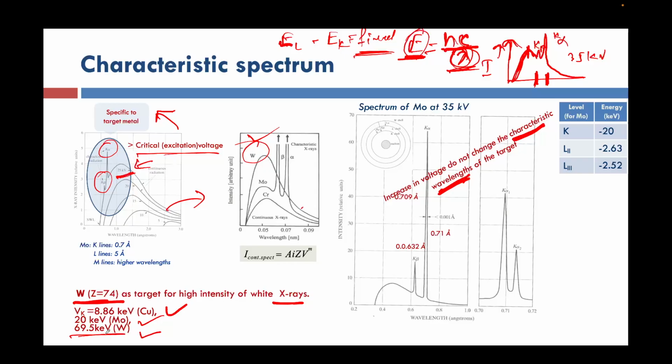This is also another reason why, as we might all have heard, in the laboratory we generally use copper X-ray. Copper X-ray is nothing but the anode, or target, material being made up of copper. This is one of the reasons that we don't have to apply very high potential, because the moment we go for high potential, we have to apply high power, and our power supply also has to withstand that limit. That is why we generally use copper.